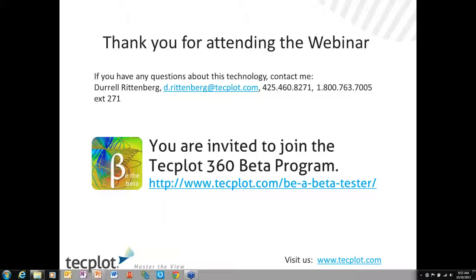It's not ideal. You'd love everyone to have a great card, but we understand not everyone does. So in that case, you turn on grid approximation, and you'll be able to rotate a coarser grid, and then it will render once you stop rotating, and it'll be useful.